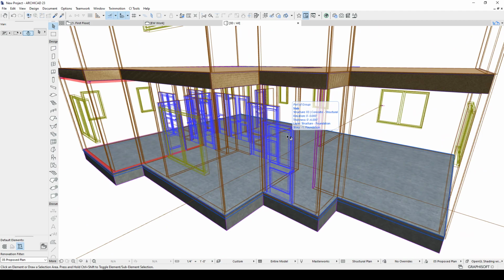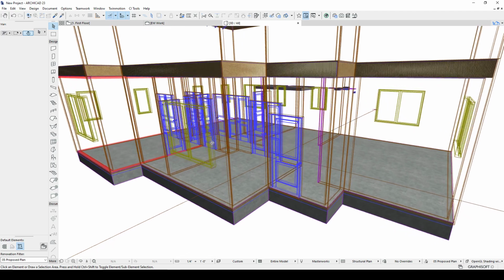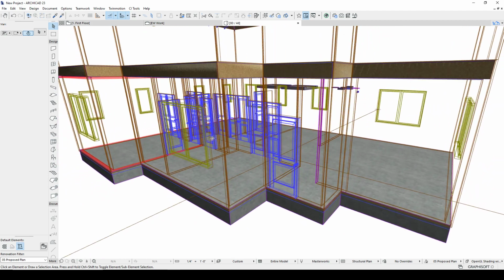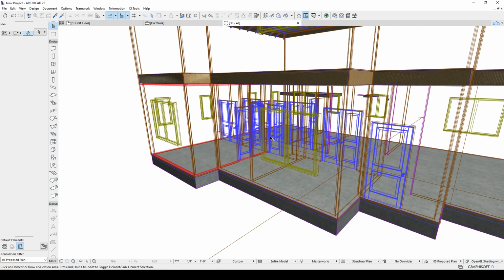We don't bother with cutting the plates out for the doors. Generally isn't an issue. The crews understand that the doors have to get cut out, and realistically they're going to get framed through to begin with anyhow. So that's how you use the plate tool, and plate tool becomes the foundation for putting in posts, studs, shear walls, door and window openings, which we'll cover in the subsequent videos.